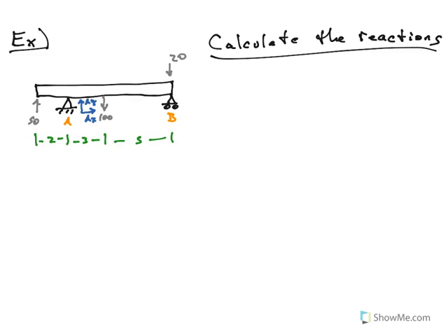Well, it's not necessarily clear, because some of the loads are pointing upwards, some of them are pointing downwards. If I don't know for sure, I'm just going to guess. I'm going to guess that the vertical one at A is up, and the horizontal one will be to the right. Okay? I'm just choosing. I don't have any insight. It's not a magical guess. You'll see if I happen to be wrong, then when I get a reaction force, it's going to come out to be negative. So I just say, okay, because it was negative, flip the direction. But if I guessed right, it'll be positive and I don't have to do anything. So I've guessed the vertical at A is up and the horizontal at A is to the right.